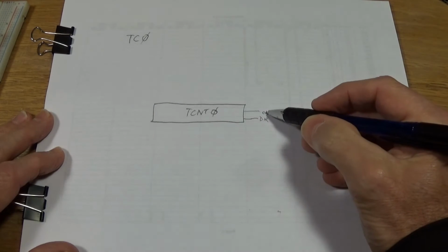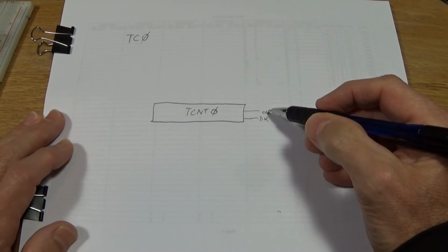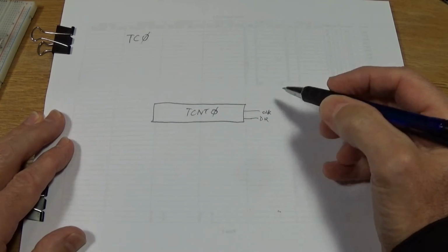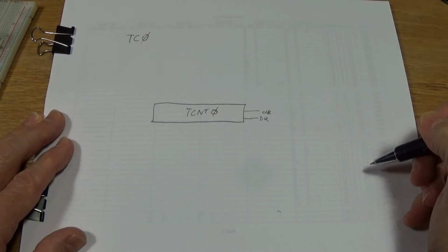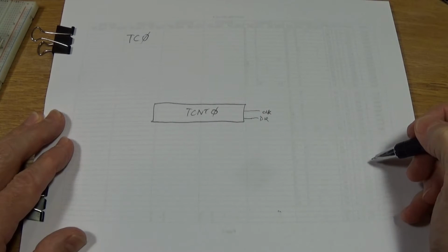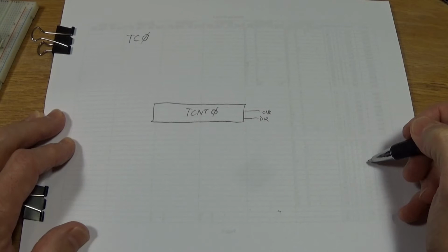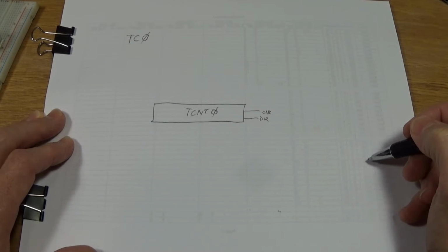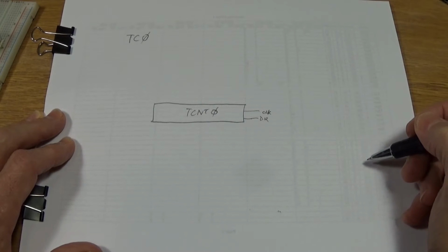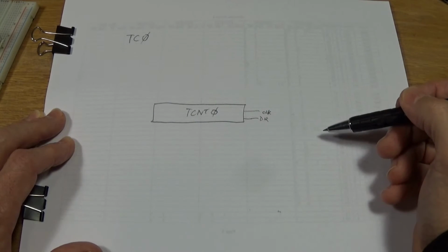The source of this clock, and this is what determines whether it's a timer or a counter, can come from a couple of different places. It can come from an I/O pin outside the chip, so it can come from a signal outside of the microcontroller, and it can run what they call asynchronously, which means it's not timed with the main timer in the microcontroller. And it can be used for timing irregular events, like what pops to my head right now is something that counts cars going down the street. So the cars go by randomly, and so it just pulses this counter every time a car goes by.